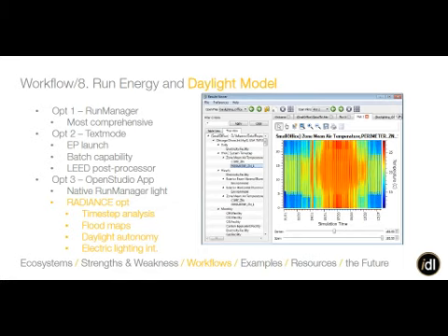So you get a whole year's worth of the performance. They'll also just give you a daylight autonomy number, so it's doing very complex annualized metrics because of the Radiance engine. And then also, probably most importantly, the script will actually take this annual run, and if you're doing daylight harvesting, it will redo the electrical lighting schedule and have that be affected by the Radiance run, which is unprecedented in general. Define daylight autonomy.